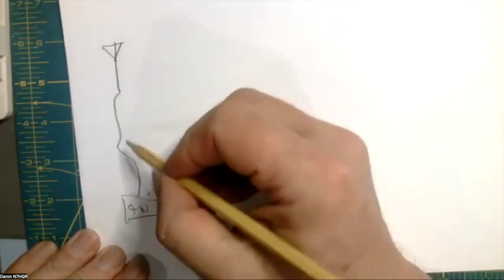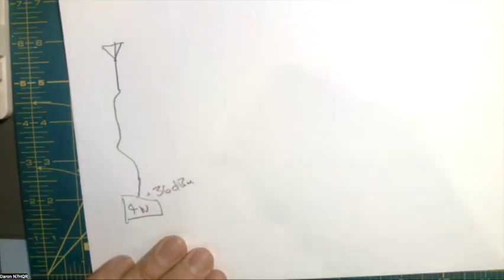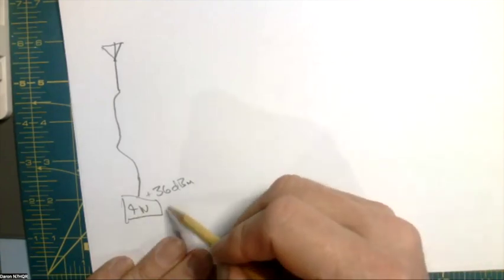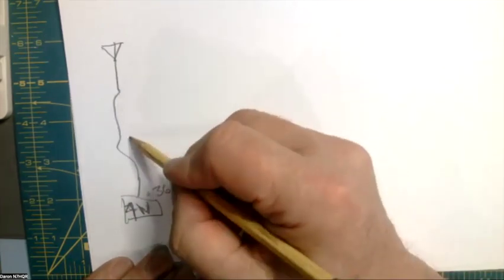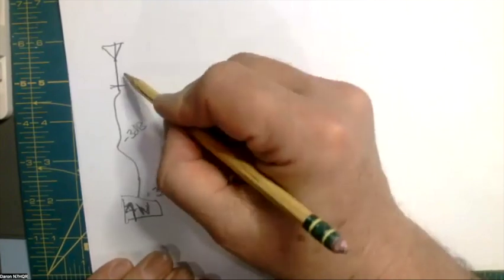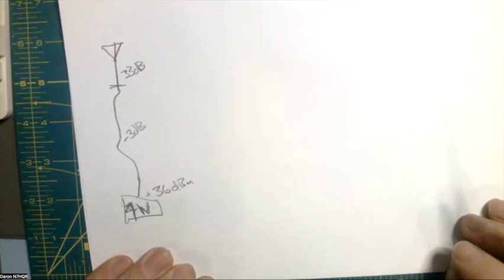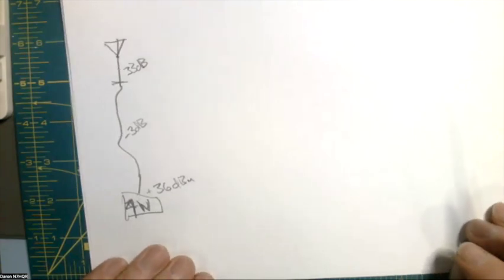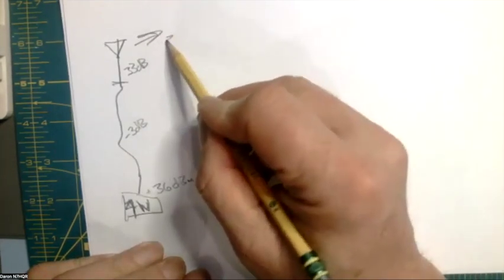Joe's trying to catch me. Yeah, so just so they don't lose track, this is an actual reference to 1 milliwatt. Yes, this is the measurement of power for 4 watts coming out of the radio. So then we're going to use a lengthy piece of feed line that's going to lose 3 dB in that feed line. So now we have 33 dB when we get up here. And we're going to use a nice J-pole or something which has essentially no gain to it whatsoever. So our signal leaving here is going to be at 33 dB.